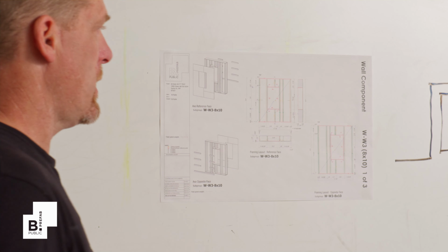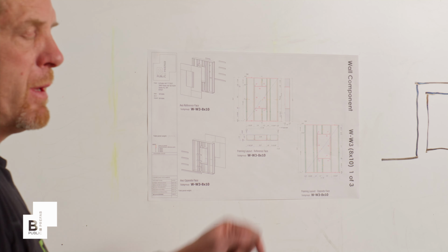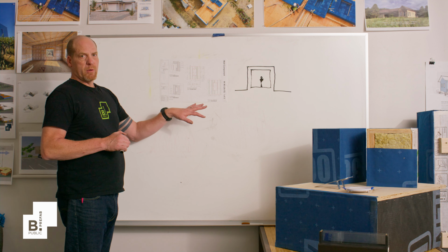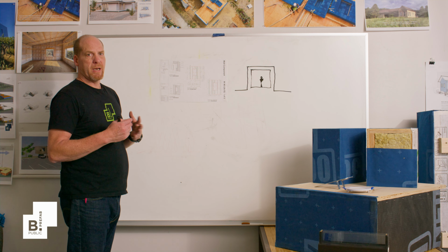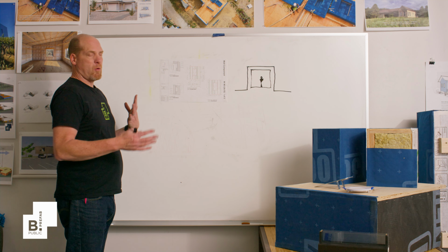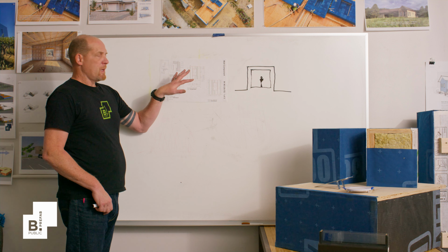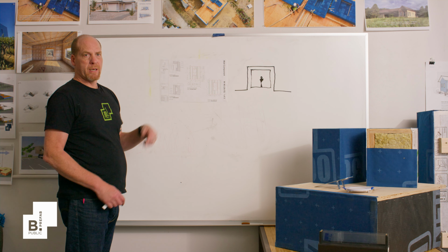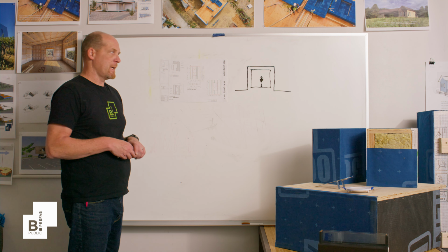So this is a fairly typical shop drawing for us. And it's all built in software that's able to export all of our materials takeoffs, as well as communicate to other automated machinery to do automated cuts, ordering. Sort of the sky's the limit. But there's quite a bit of very real technical data that's in a shop drawing, beyond just delineating what the size is.